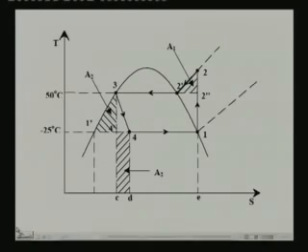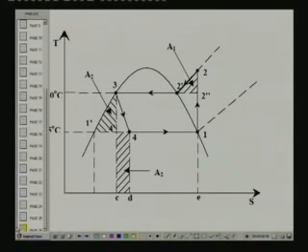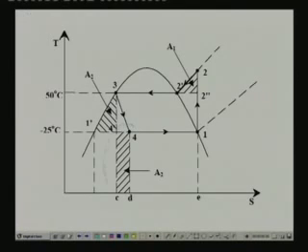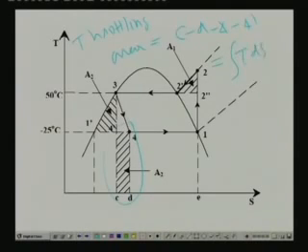Okay, throttling area can be obtained in two ways. The first way, if you are finding the proper throttling area, is nothing but the rectangular area CD 4 dash, and this is equal to, if you are applying integral TdS, temperature remains constant, integral TdS from 4 to 4 dash. So this is simply equal to TE into S4 minus S4 dash. Again we know all the entropies, so you can easily find out the throttling area using this expression.